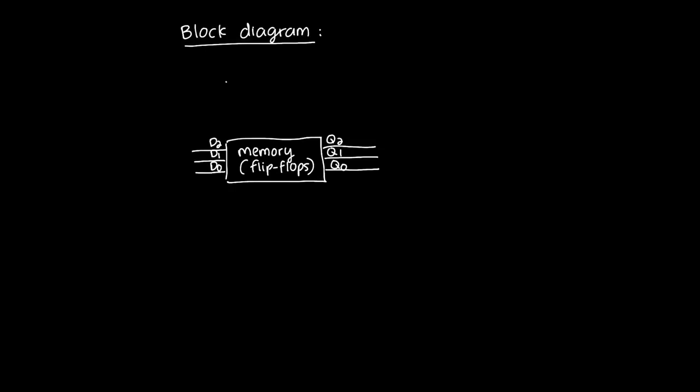So separately up here, I also have my control logic, and this was the result of those Boolean expressions. Q2, Q1, and Q0 are in fact my counter output, so it's the output of my system in this case because I'm just building a mod-8 counter.